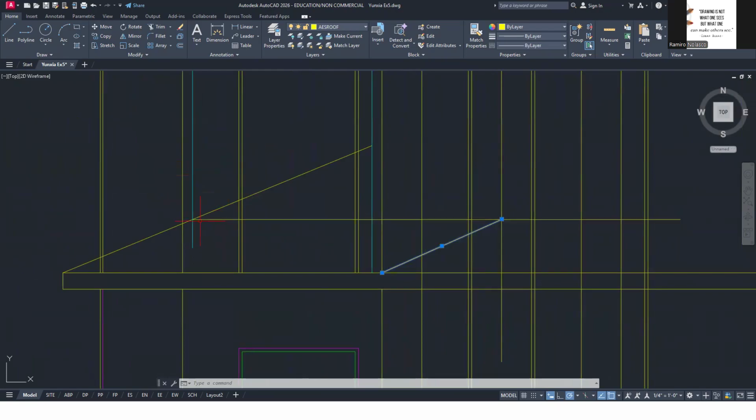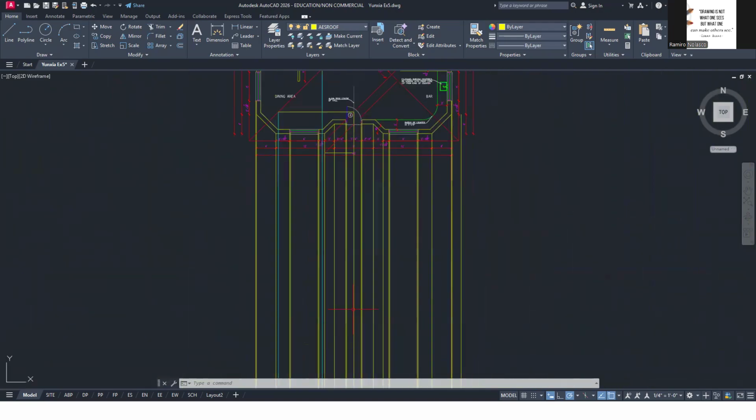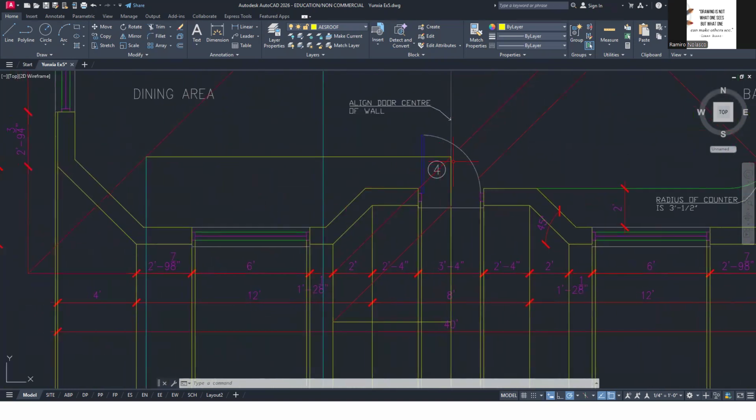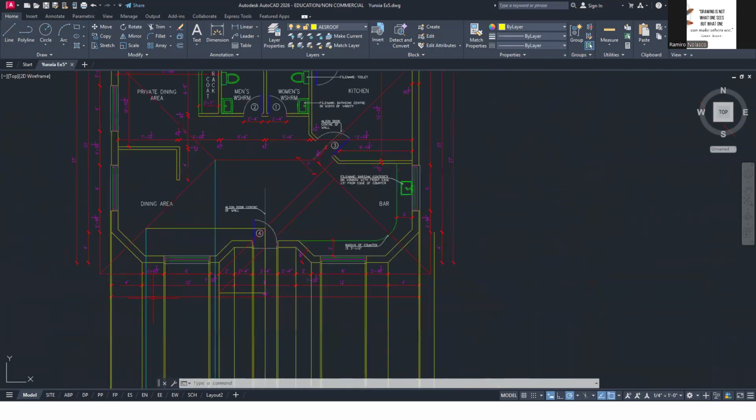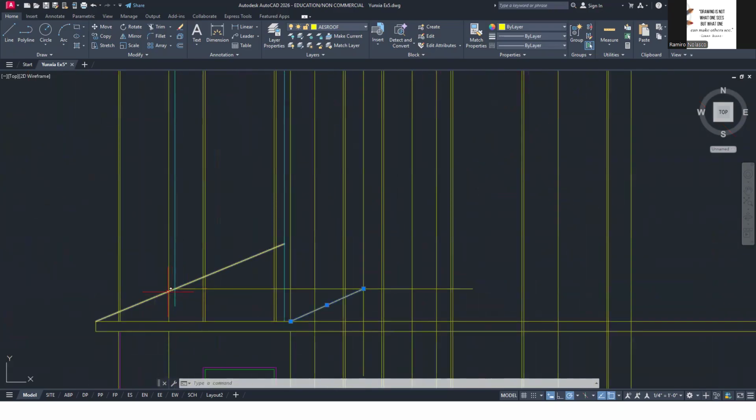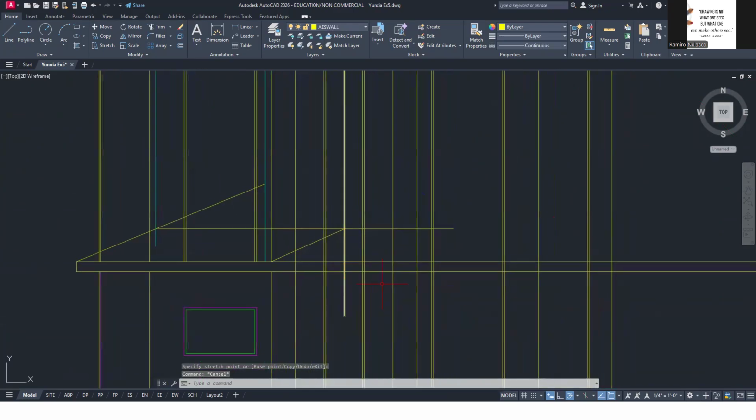Because when you project this here, right, it says at this point, that's where my canopy should meet. So this one has a little steeper slope. Does that make sense? See, at 45-degree, imagine this sloping, right? And you make a horizontal line, it meets this 45-degree angle. We project it down, it meets our slope, and then we project it back. That's where it meets. Make sense? Okay. I'll stop there for now and allow you to catch up.